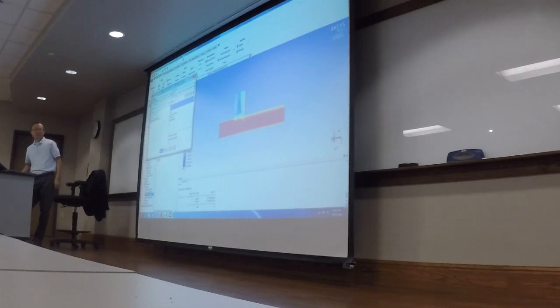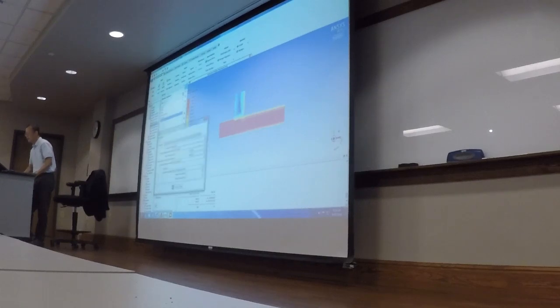Well, you may say, well, how about, we still have 2 minutes, so let's quickly run this. Let's change the boundary condition. Go to boundary conditions. Inlet 1. Instead of 1, let's make it 0.1. Okay. Now we'll go to initialize. Initialize. Do you want to discard the data? Yes. Then run the calculation. Go. 600.